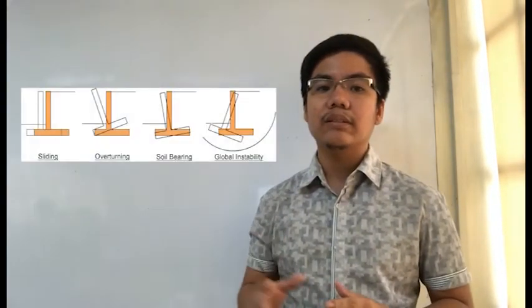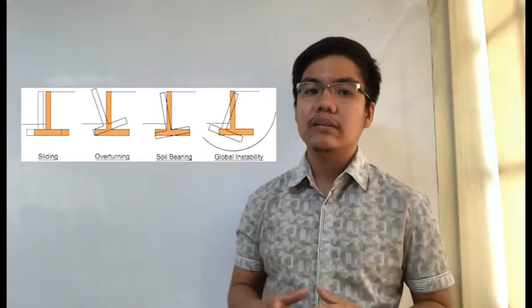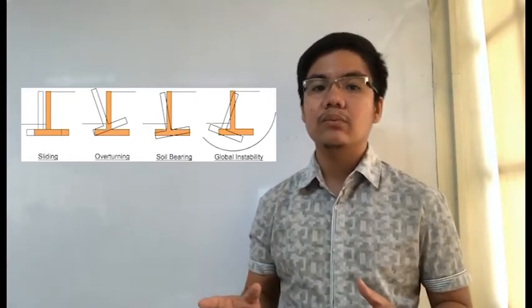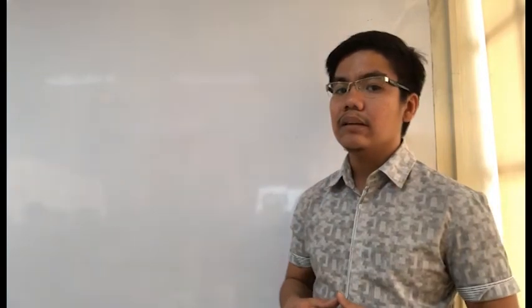As an example, the National Building Code of the Philippines requires retaining walls to be designed to ensure stability against overturning and sliding, excessive foundation pressure, and water uplift. They have to be designed for a safety factor of 1.5 against lateral sliding and 2.0 in overturning.